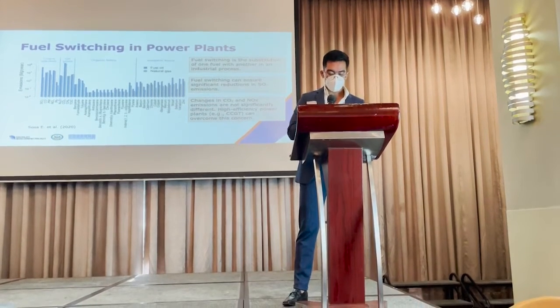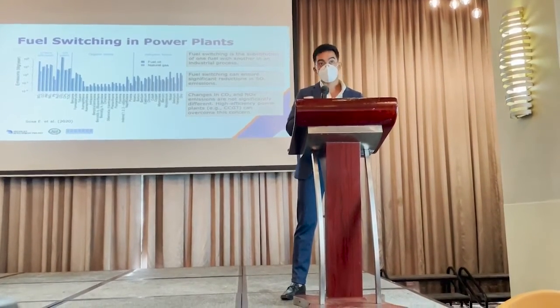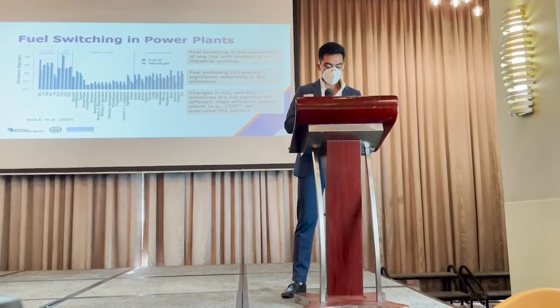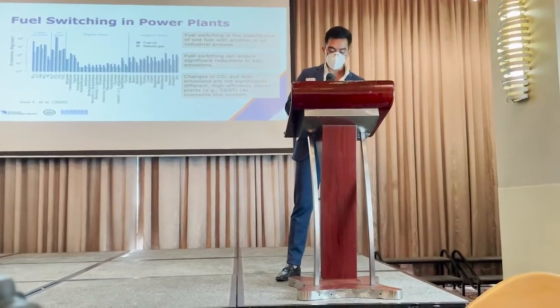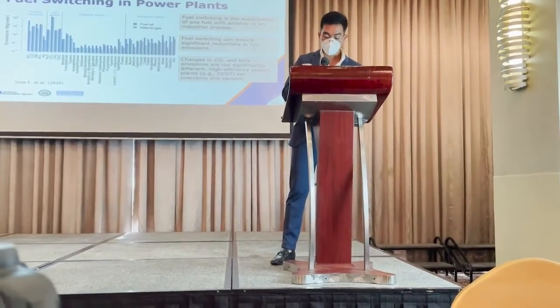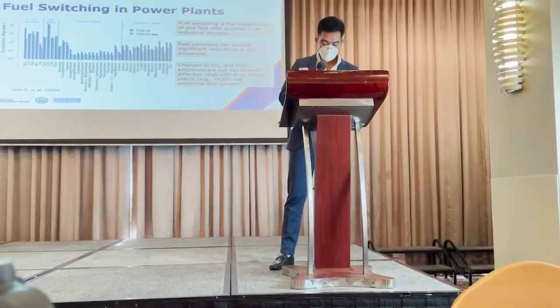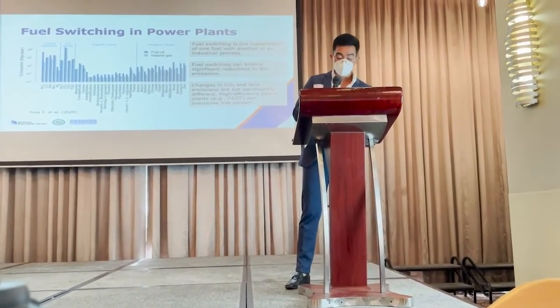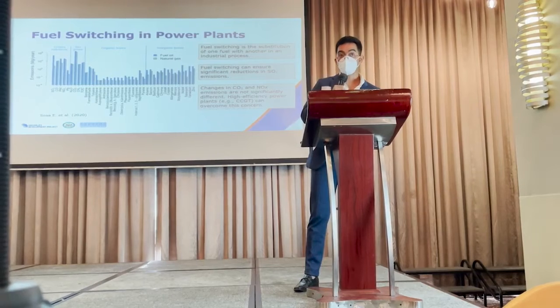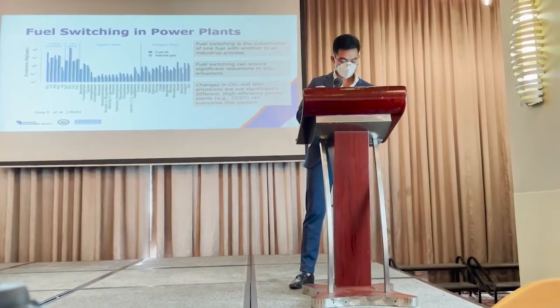This is because of the lower heating value of natural gas, and that means that a larger volume of natural gas would have to be combusted to generate the same power offered by fuel oil burning. A workaround in this concern is to operate high-efficiency gas-fired plants or to adopt carbon capture and storage.